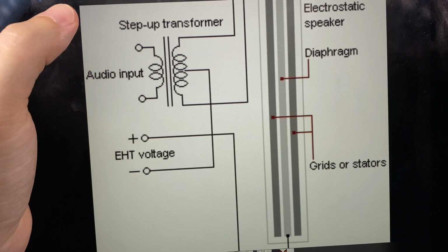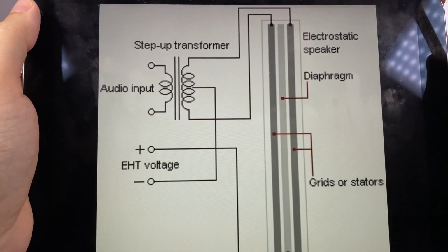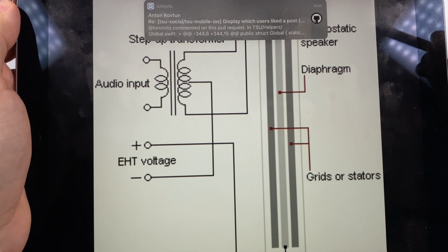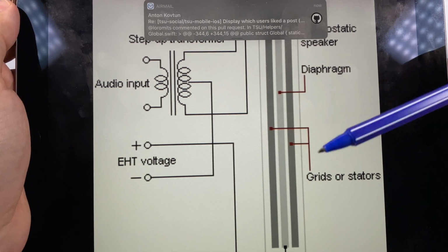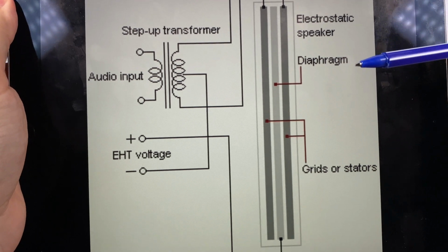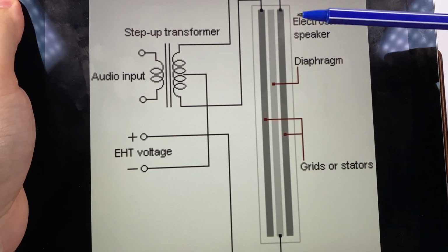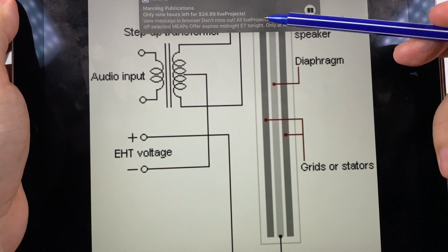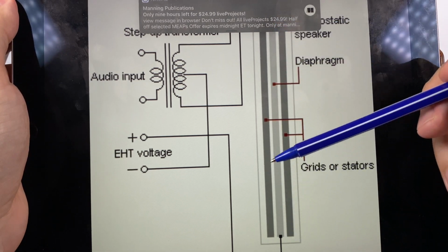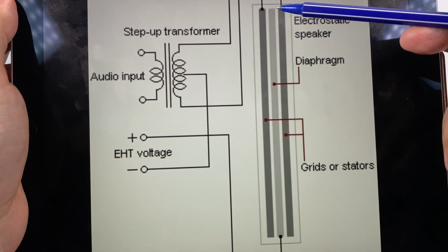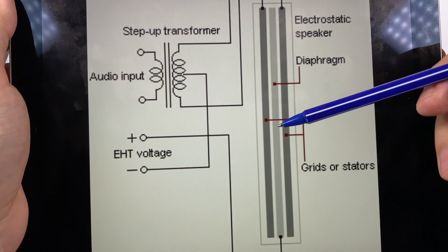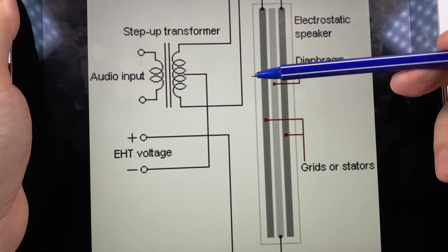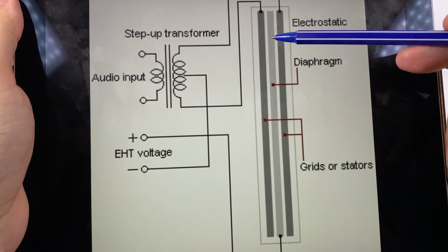Next, really popular in high-end schemas are electrostatic speakers. The basic idea here is pretty simple. Let's take two metallic grids and put some thin film between them. Usually it's made of mylar or some other material, and then we apply really high voltage to these grids.